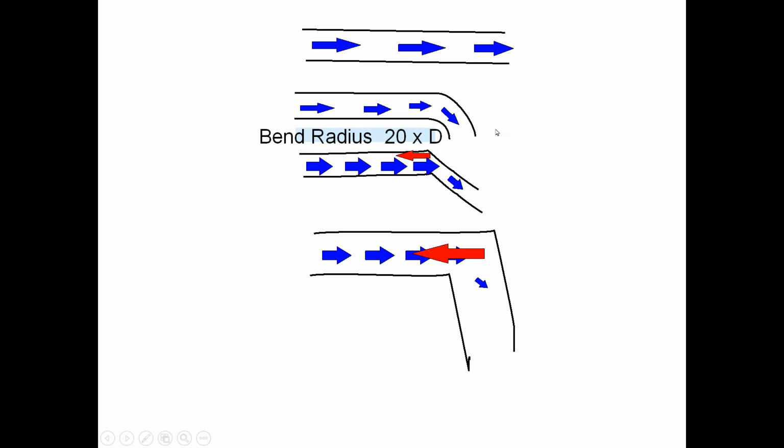If a wire is 1/8 of an inch thick, 20 times that is where you can safely bend it without losing any of the RF signal. But as you begin to make different kinds of bends, you begin to get a reflection backwards. And if you ultimately make a right angle, which is what RF does not want to do, you will eventually lose all of your signal.